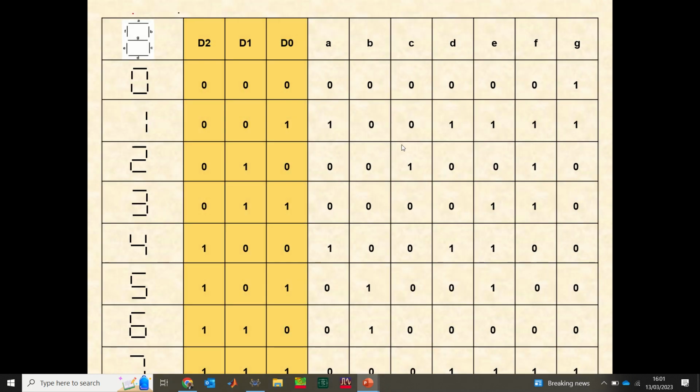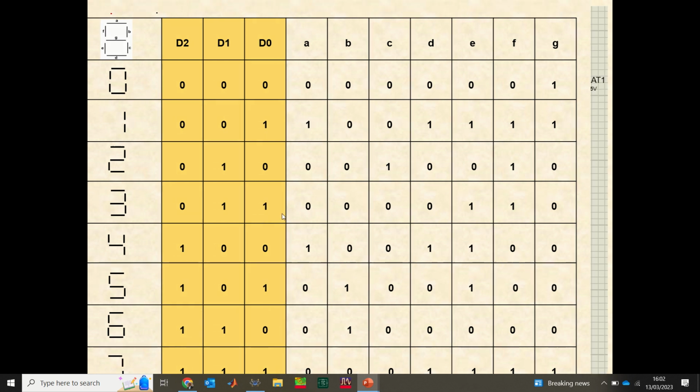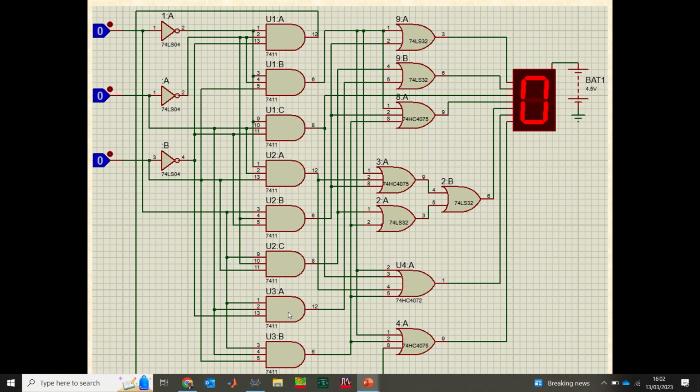If you're used to electronic design, this shouldn't be a problem. So all you need to do is that I'll go for A. So first of all, let's look at how we activate A. Look at A. For A, I only have one at the second AND gate, that is 001. I have one there, and of course I have one again at 100. This is 1, 2, 3, 4, 5. So I have one at 2 and 5. So we count from the top.